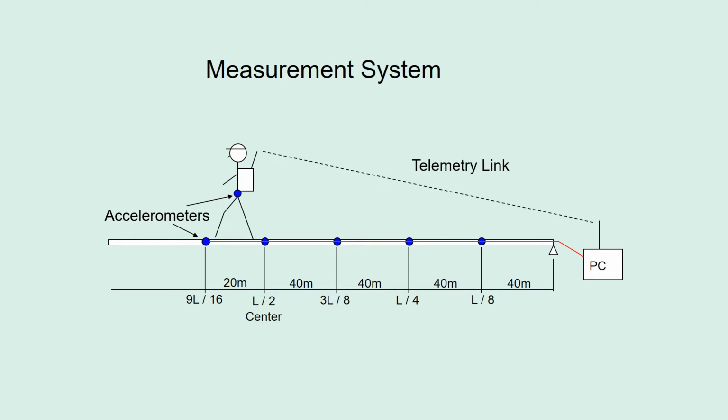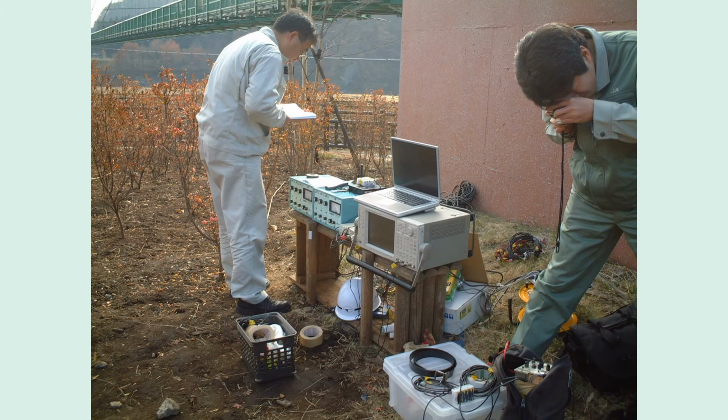We found that pedestrians synchronized to walk on the T-bridge, but the interaction between pedestrians and the girder movement was not clarified. That's why the accelerometer was attached to the pedestrian. All the measured data were collected and stored in the data logger and the PC.